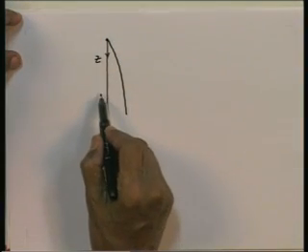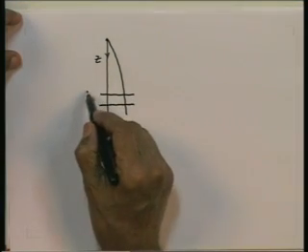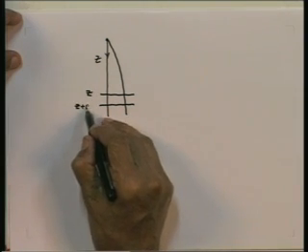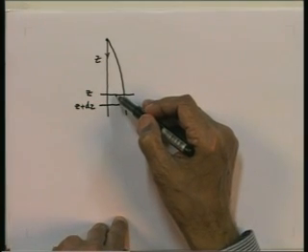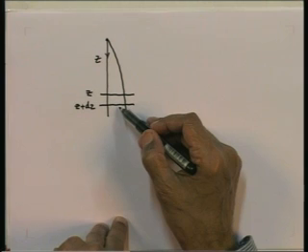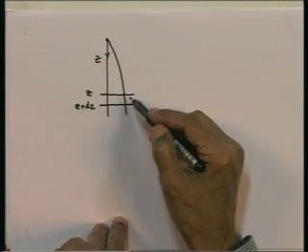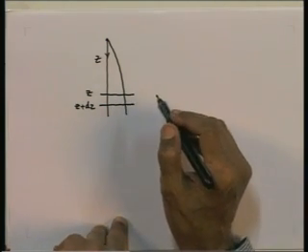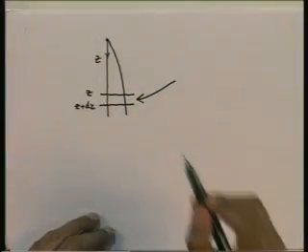If you have a cross section at z and a cross section at z plus dz, then from z to z plus dz, the mass flow rate per unit width increases by an amount rho squared g by mu delta squared d delta. And where does that increase come from? That increase comes from the fact that we have condensation taking place.